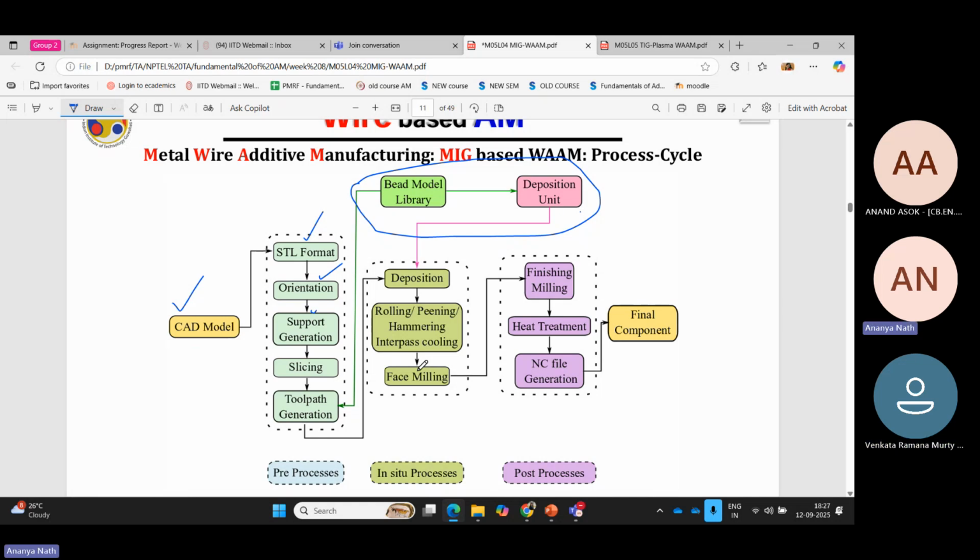I can give you one value. In case of aluminium, the melting temperature is 662. It will go above 660, around 900 or so. Just after the deposition, we check the temperature for each layer and it comes around 300 to 400 degrees, because of the fast cooling, it cools down that easily.